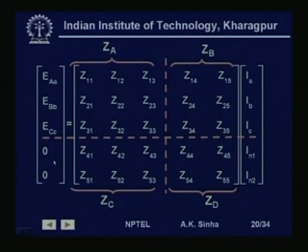This voltage is going to be equal to the impedance multiplied by the current, which gives the voltage drop across the 2 points. Now, here the impedances will be Z11, Z12, Z13, Z14, Z15. All these impedances will give a 5 by 5 matrix, and the currents will be the 3 phase currents I_A, I_B, I_C, I_N1 the current in neutral conductor 1, and I_N2 in the neutral conductor 2.